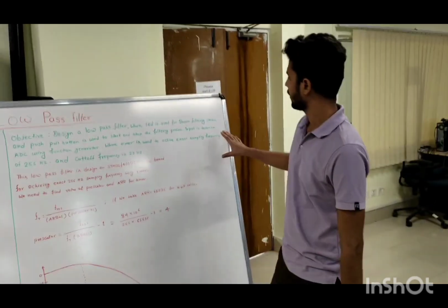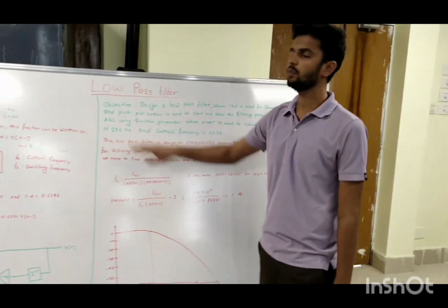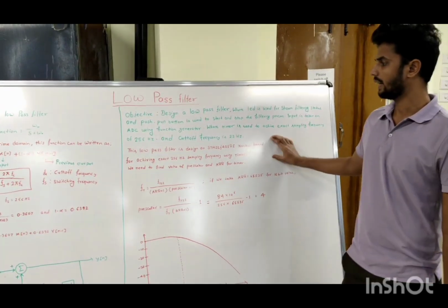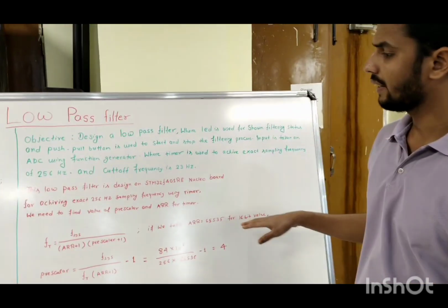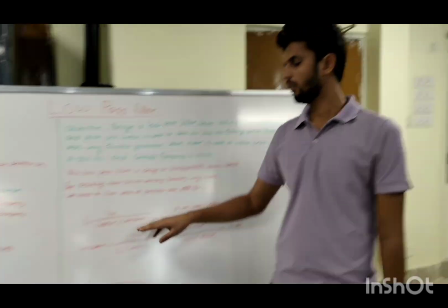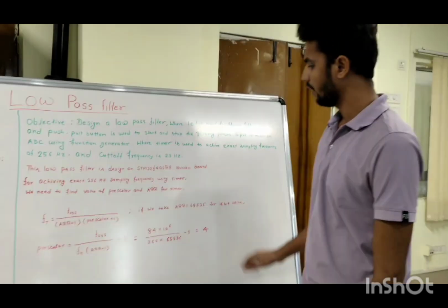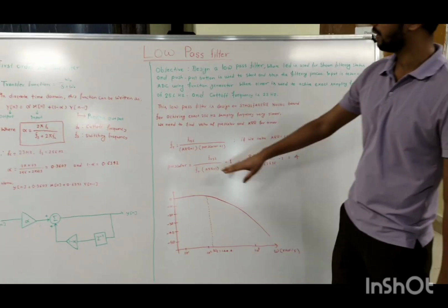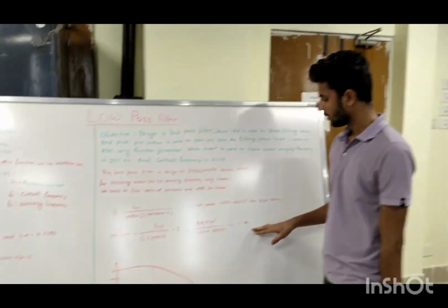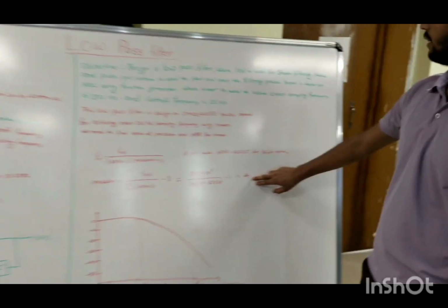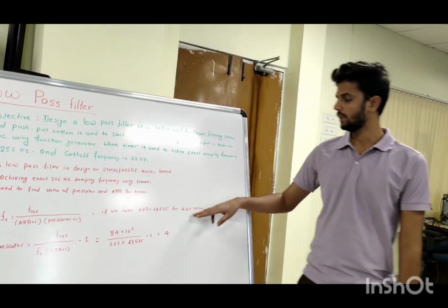Now come to our objective. Here we need to first achieve the sampling frequency of 256 Hz. We need to generate a timer where that timer will exactly give the sampling frequency of 256 Hz. So for that we need to set the value of the pre-scaler and the auto reload register ARR for that timer. The value of pre-scaler and ARR will be evaluated using this formula, where pre-scaler is equal to f system divided by ft into (ARR plus 1), minus 1. So from there the value of pre-scaler is 4. Actually I am using 65535 for ARR, where ARR is used to count a 16-bit value.